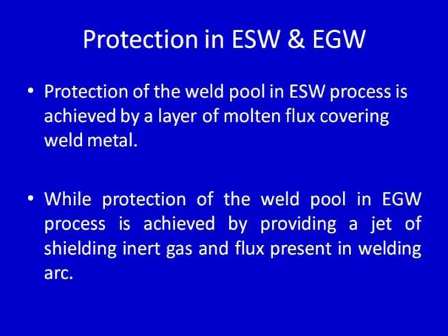In the case of the electroslag and electrogas welding processes, different approaches are used, but both these processes are mainly used for very thick sections. Both these processes are based on the vertical uphill welding concept, where in one go the weld joint is completed in very thick sections, which can be as high as 70 to 80 centimeters or more.